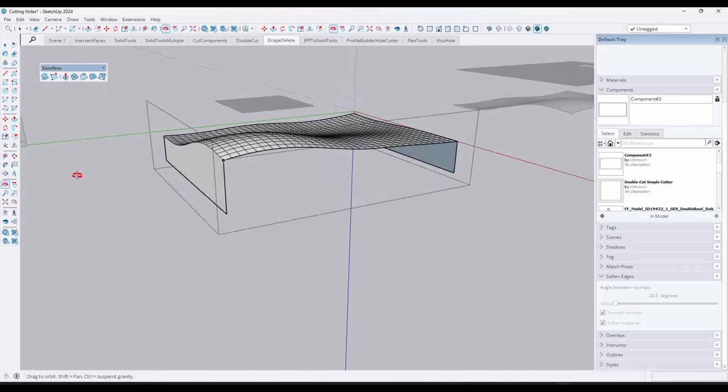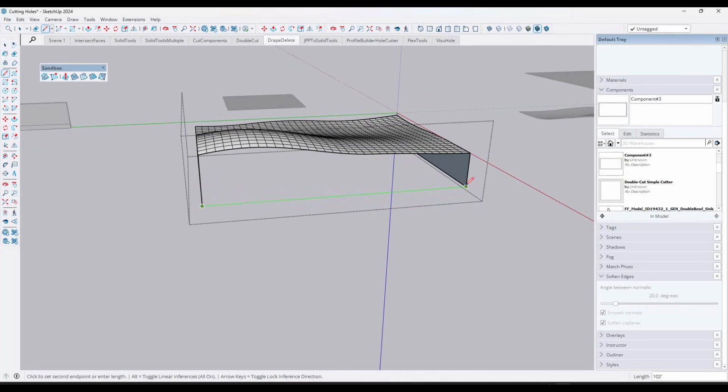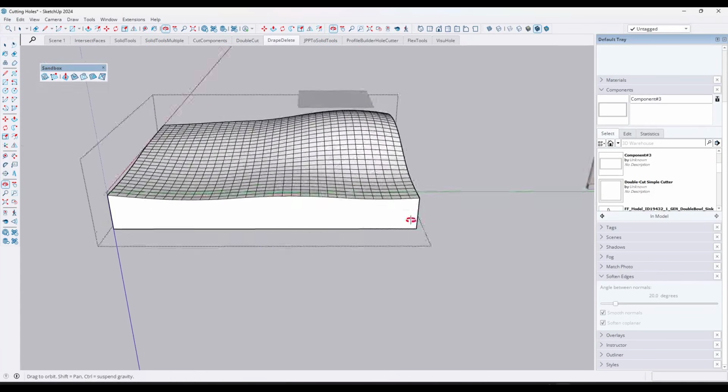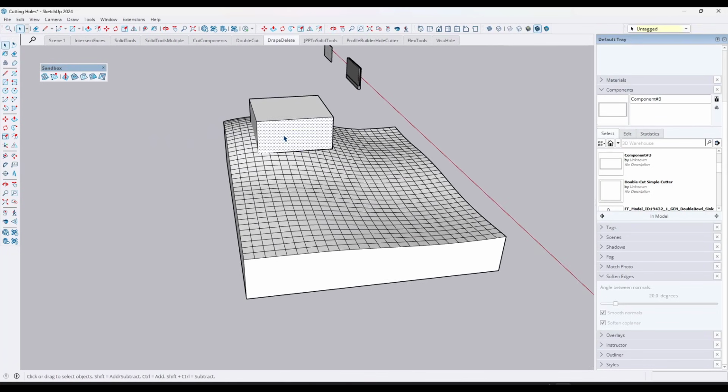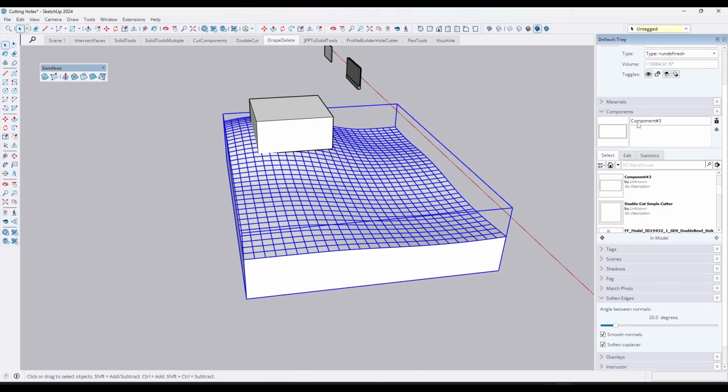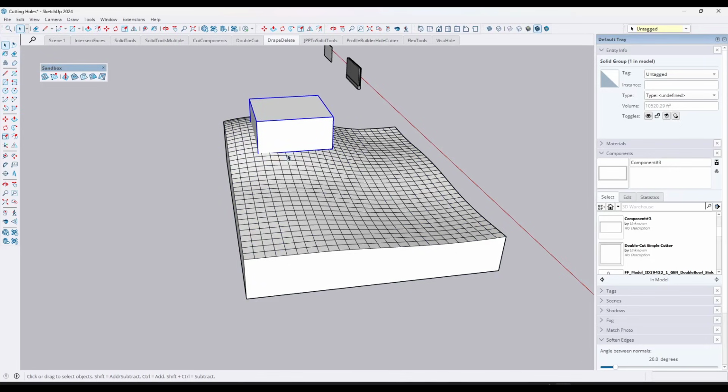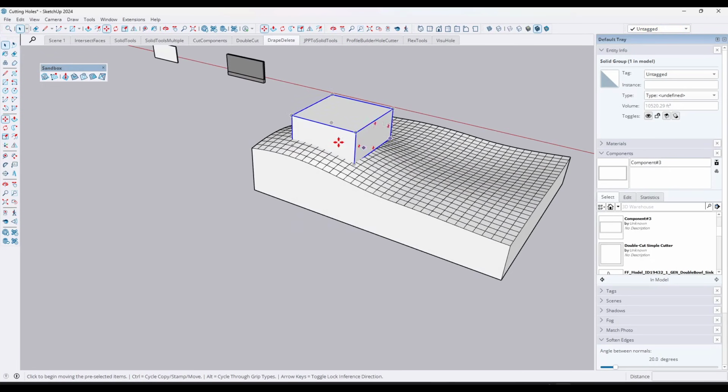You can also use the Joint Push Pull extension to push-pull this down and flatten it. But in this case, say that I wanted to use this as the footprint for a building, and I also wanted some walls in the back. So I'm just going to make this a group right here. Notice how both of these are solids, so that means I can intersect them together.